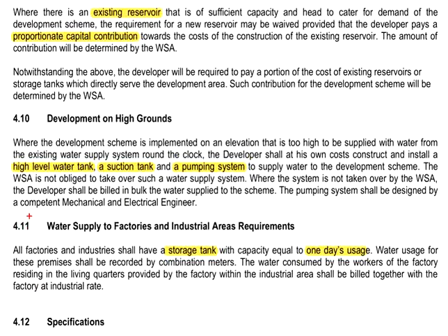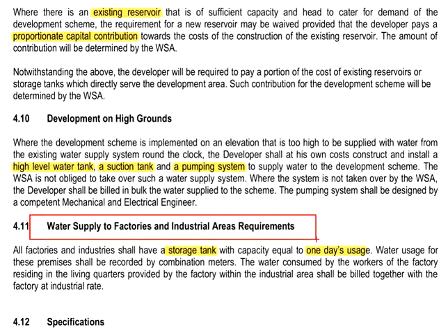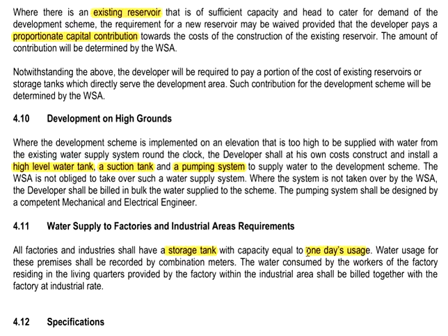As for the water supply for factories and industrial areas, a storage tank shall be provided with a capacity equal to 1 day's usage. That is the bare minimum.